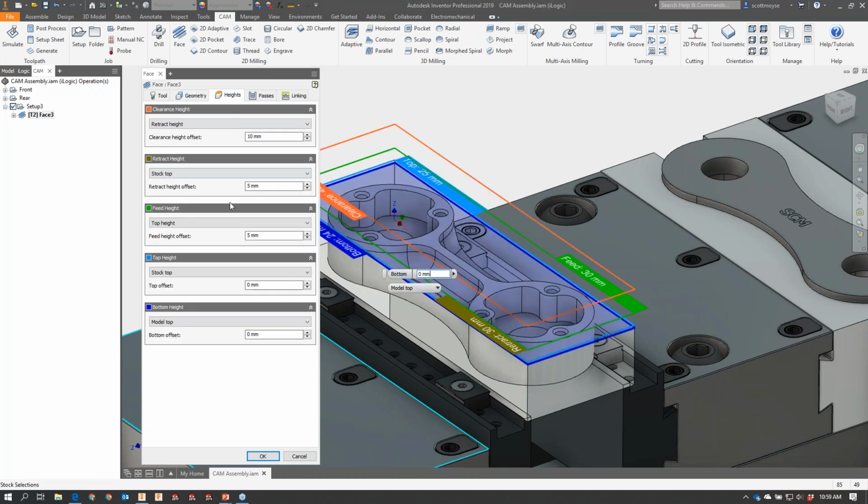So typically containment in the X and Y plane when you're looking down onto your job. And then the third one is your heights. So containment when you're looking in elevation. So you only want to generate cutting toolpaths between an upper and lower Z height, but not above that or below that. Then you can control how the tool moves from one toolpath to the next, or from one pocket to the next.